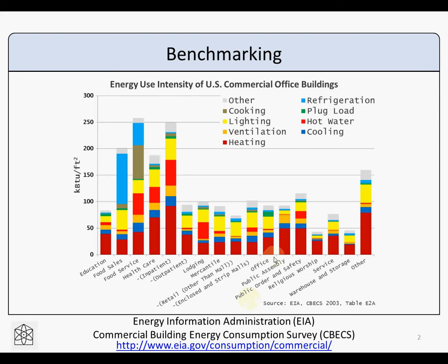We are probably interested in education or office buildings, and as you can see, heating use is the biggest component of that, and lighting is as well. And we're targeting energy use intensity, which is a unit of total energy use divided by the floor area. In buildings, it's not perfectly linear to assume that as you increase in size, the energy use increases linearly, but it's pretty close. So EUI, as it's used, is a good way to compare buildings.